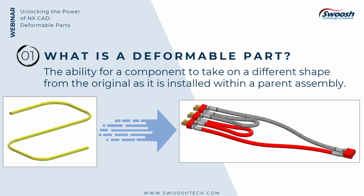Deformable components are very useful objects since NX allows a component to be designed in one state and deformed into place in the context of a parent assembly. Some simple examples of these types of parts would be O-rings, springs, or hoses. These are manufactured in one shape, then stretched, bent, or compressed into place at assembly.